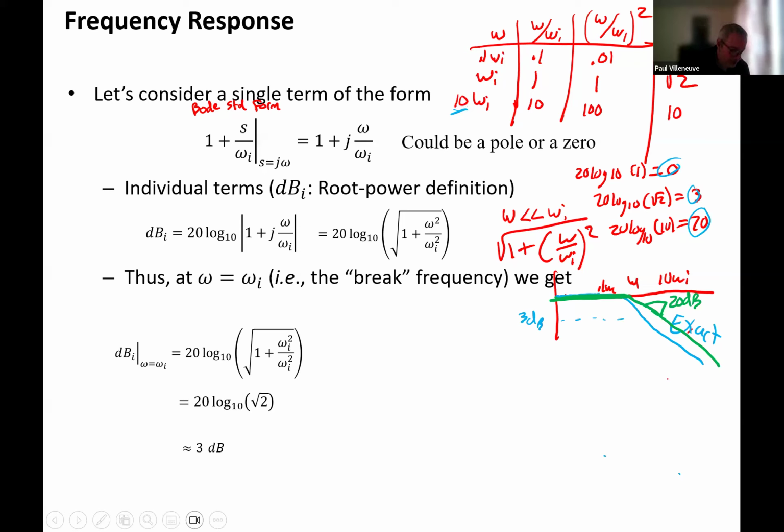So the slope that I have here is going down at 20 dB per decade. A decade, that might be a new term, is equal to multiplying your frequency by 10. So a frequency that is multiplied by 10 is a decade above. So 10 hertz is 1 decade above 1 hertz. 20 hertz is not 1 decade above because you've only doubled the frequency, right?